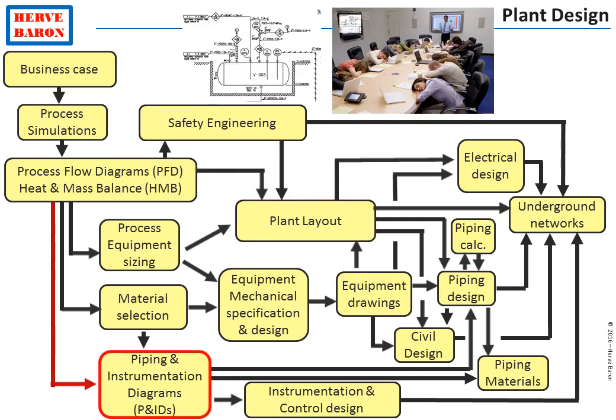The most important document in a process plant are the piping and instrumentation diagrams. Freezing such diagrams at an early stage is required in order to allow piping design and instrumentation and control design to progress and proceed. Therefore, P&IDs must be reviewed between the engineer and the owner at an early stage. This is done during the P&ID review meeting, which is also an essential step in the development of the plant design.